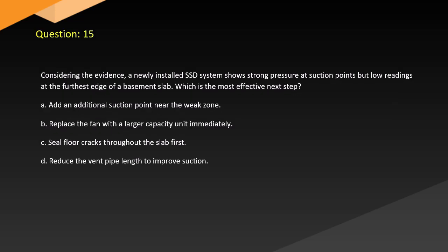Question 15. Considering the evidence, a newly installed SSD system shows strong pressure at suction points but low readings at the furthest edge of a basement slab. Which is the most effective next step? A. Add an additional suction point near the weak zone. B. Replace the fan with a larger capacity unit immediately. C. Seal floor cracks throughout the slab first. D. Reduce the vent pipe length to improve suction.